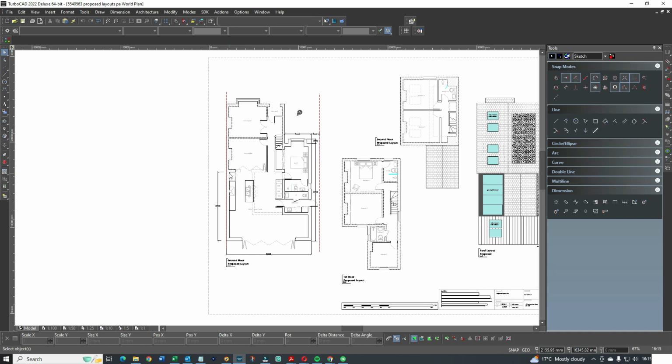So the rules of the party wall, this is to do with excavations. If we excavate to build another building, or if we excavate below the foundations of the existing property, we need a party wall agreement with the neighbours if that excavation is within 3 meters of their property.